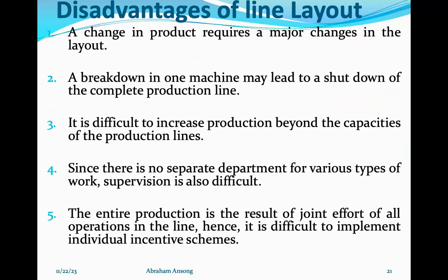Disadvantages: a change in product requires major changes in the layout. We said the layout is standardized. So whenever there is a need to change the design of a product, it brings chaos to the process. Major changes must be made to the layout to meet the new changes. It's different from the earlier type of layout where you can simply adjust things to suit customer orders and specifications. With this type of layout, there is standardization, and whenever you want to move away from it, it comes with major changes.